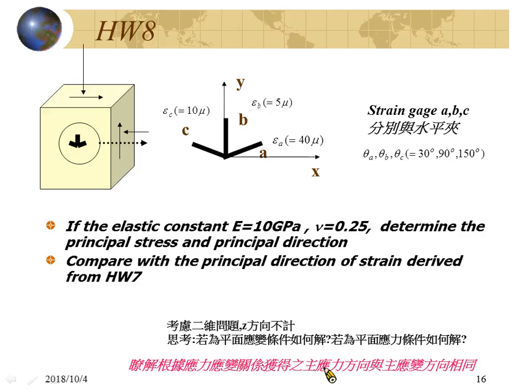Can you evaluate the strain tensor? Yes, right? If you have the strain tensor, you can calculate the stress tensor increment using the stress-strain relation. Then you will have a stress tensor. Since you have a stress tensor, you can evaluate the principal stress and principal stress direction.